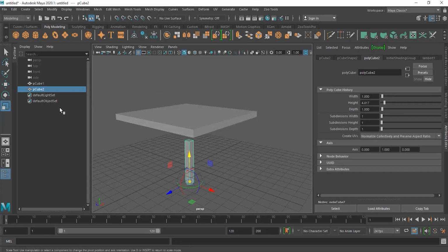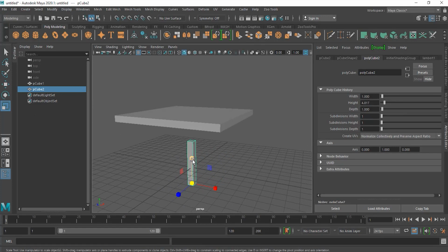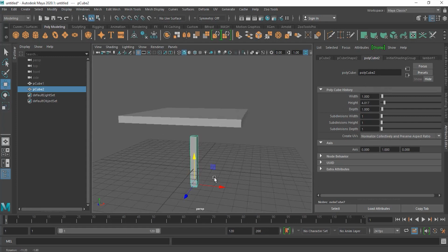Okay, now I will press D again, so it's normal. So if I change the height from here, okay, I think it's better if I do it from the scaling here, because here it's pretty much the same thing. It basically ignores the attribute editor. If you don't delete the history, it actually ignores your pivot point. So let's not do it from there, just do it normally from here.